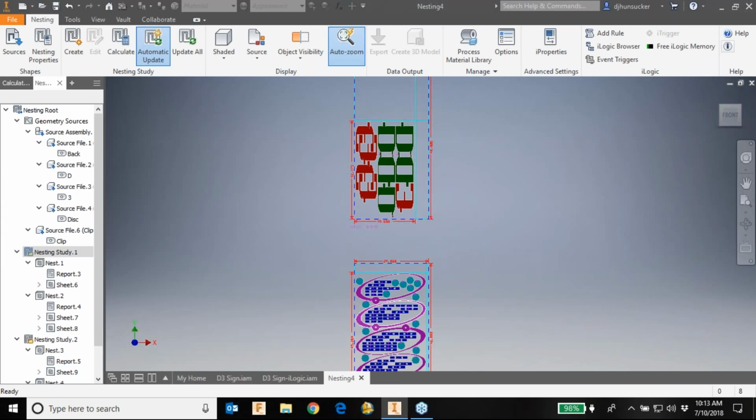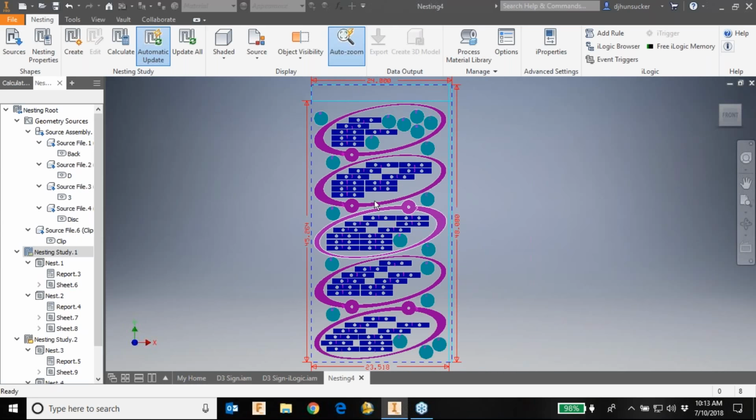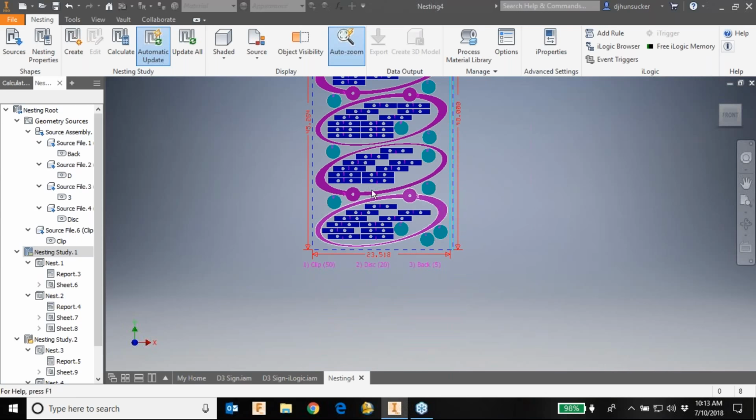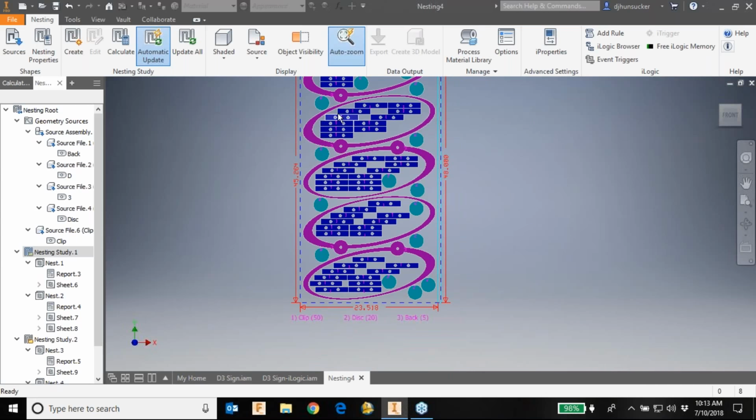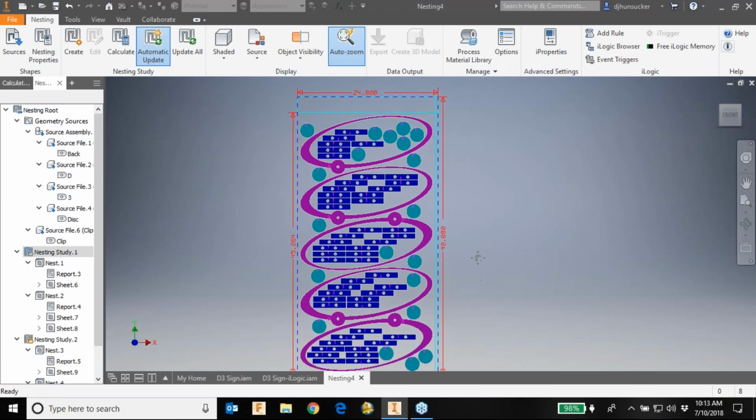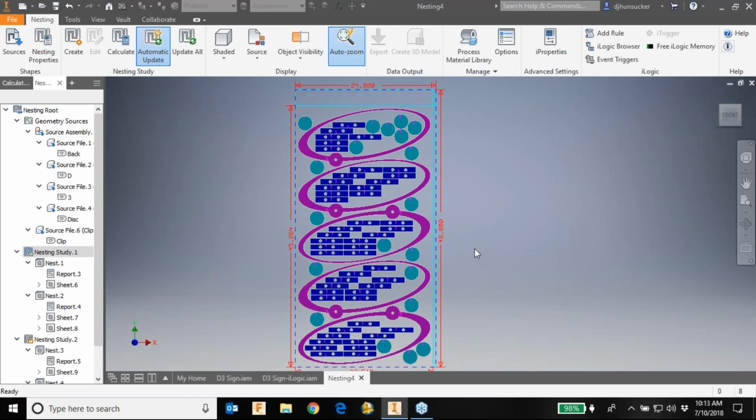So same scenario here, but since I told it I wanted 10 and I said 5, we're going to have 50 of those plates. So you can kind of see that it recreated this and said, okay, well, I'll fit all these in here, and actually it looks like a nice setup in there. So that's kind of using a lot of my space. There's still some that I could probably sneak some other stuff in there, but that's where it's nice that, yeah, I started from the assembly, but you can also add extra parts in there if you know they're the same material, same thickness, and so forth.